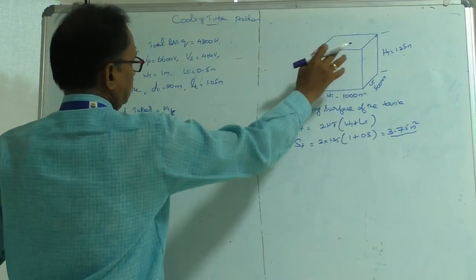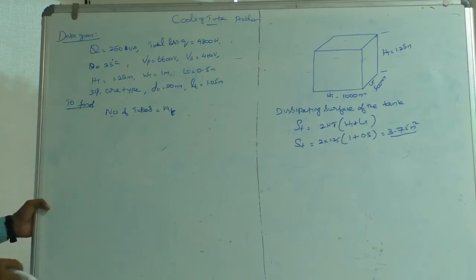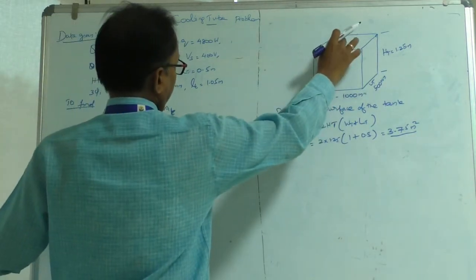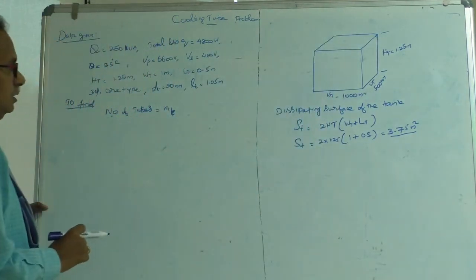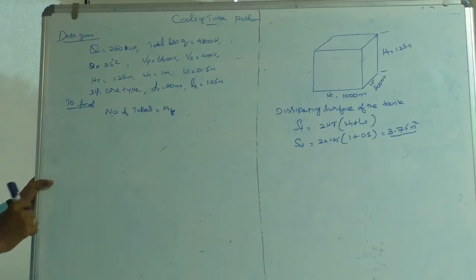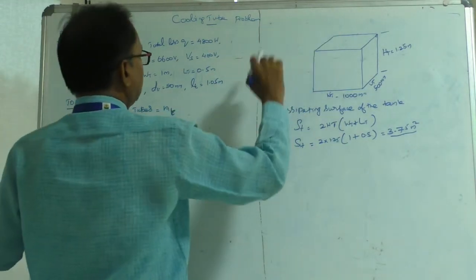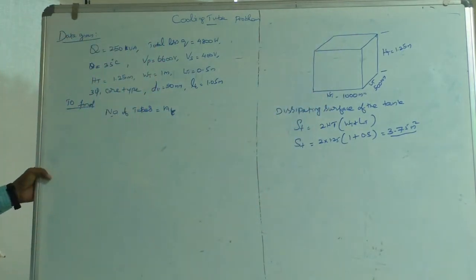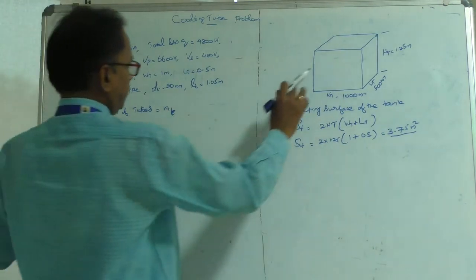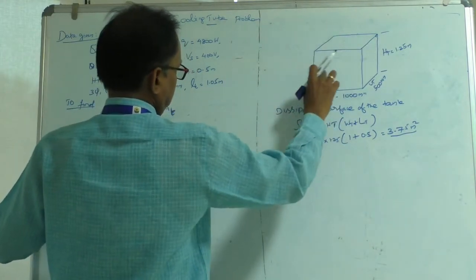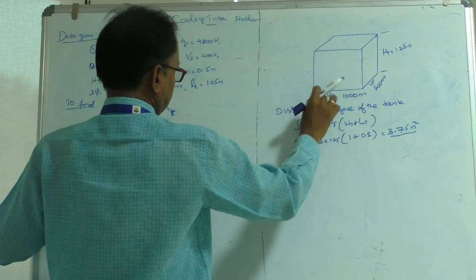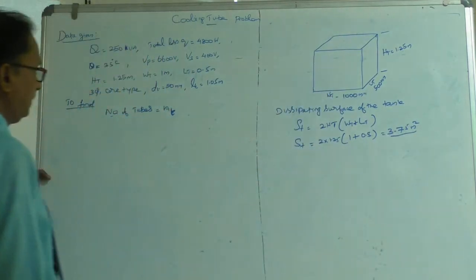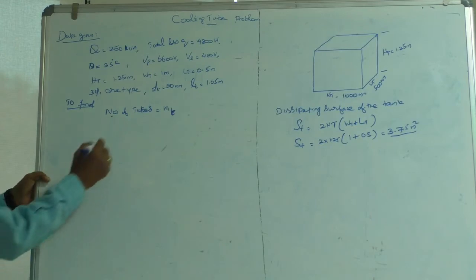On the top side also, the chances of air falling on it are very minimal, so generally they neglect this top area. Unless they have specifically mentioned it, you don't need to calculate it. In some cases, they ask you to take only half of the area as useful for heat dissipation. In this problem, we are calculating only the 4 vertical sides, which yields 3.75 meters square.